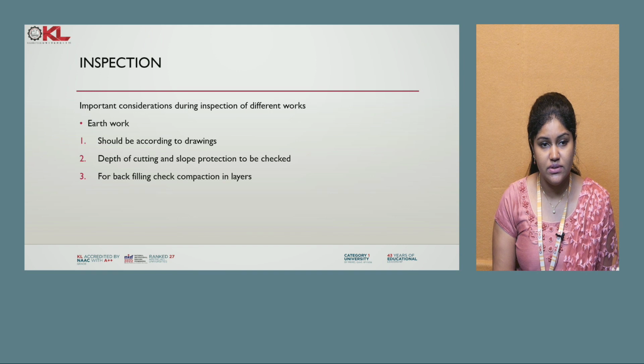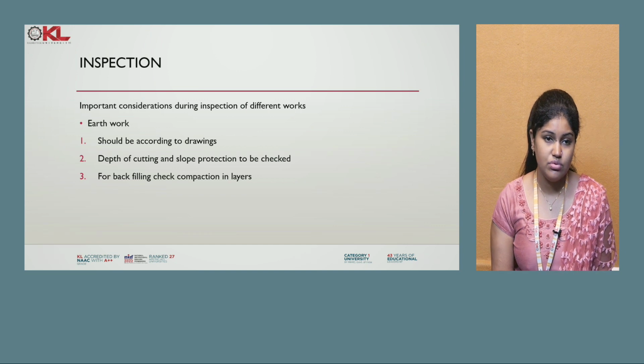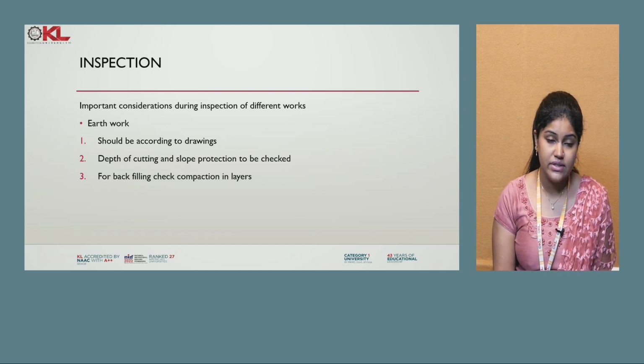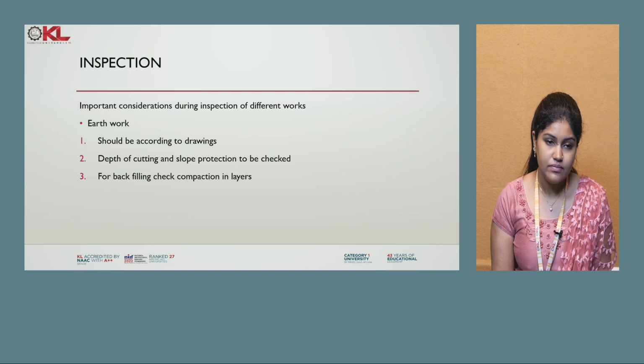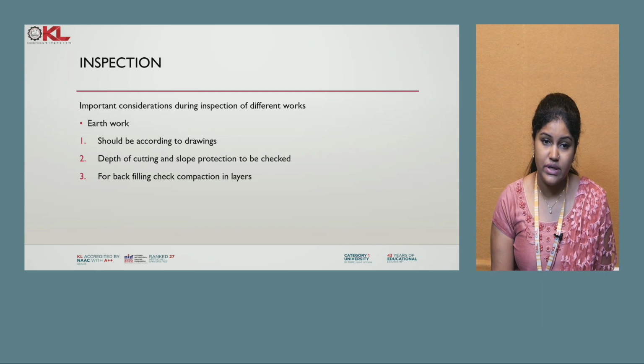First one is the earthwork. Earthwork should be according to the drawing, depth of cutting and slope protection to be checked, and for backfilling check compaction in layers. So these are the three things we need to monitor or inspect in the earthworks. First we have to go based on the drawing. Second one, the depth of cutting. What is the depth of cutting? What is the slope protection required? We need to check that. And if there is any backfilling, we have to check the compaction in the layers.